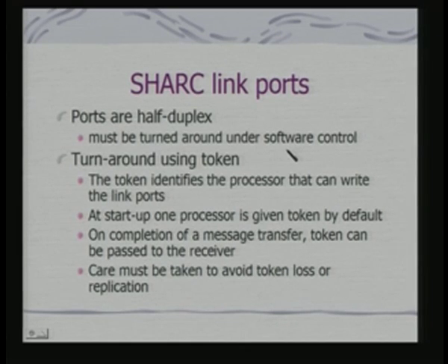Typically, a token based protocol can be used. The token identifies the processor that can write to the link ports, and the token is stored in a memory location local to that processor. In fact, these processors are also not sharing any memory among themselves.